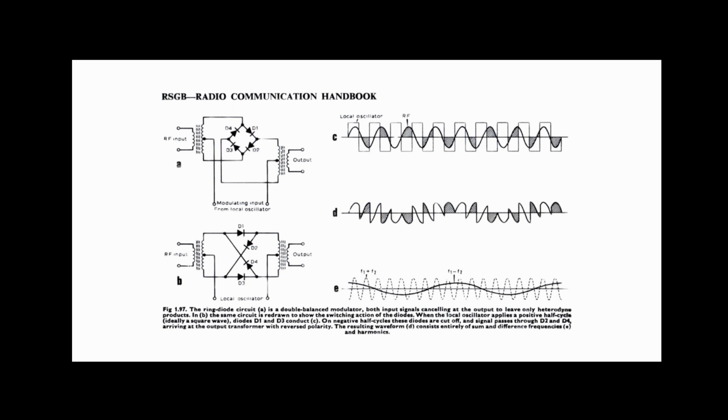Well, we really need intermodulation. These mixers actually work with intermodulation, and it's the intermodulation that gives us the desired F1 minus F2 and F1 plus F2. It's all those other ones, related to the odd harmonics and the even harmonics of all the signals that come in, that we're not interested in. And for our upconverter, we're interested in the second one, the F1 plus F2. So we need to get these diodes turned on very fast if we want a strong mixer.